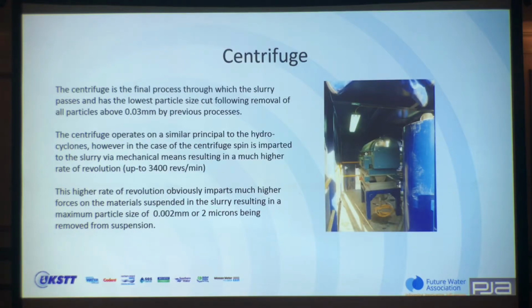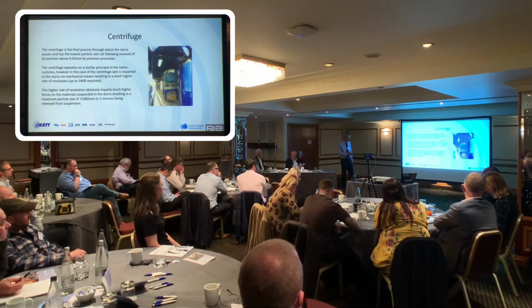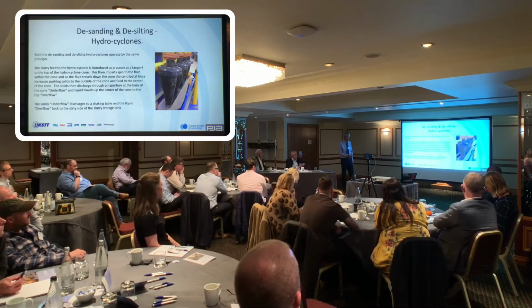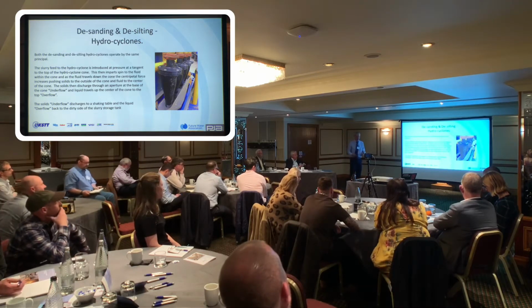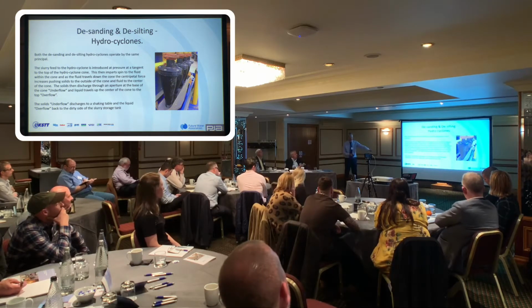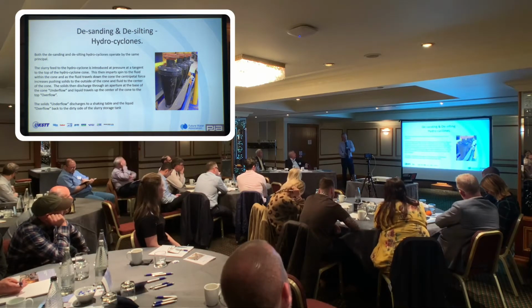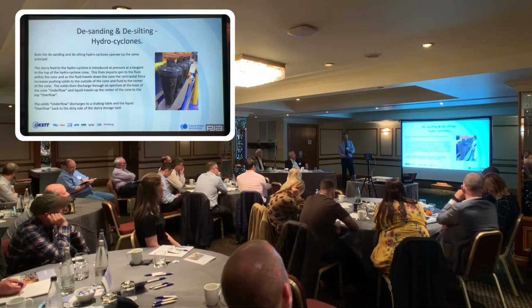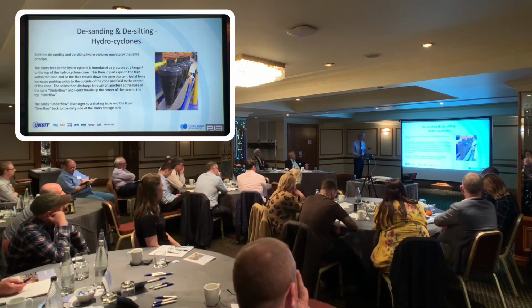The last process, or one of the last processes, is using a centrifuge. In fact, I missed a process. Yes. So all of these processes will discharge onto a fine screen. And what usually happens is that you get a filter bed on the screen. So if there's sand particles within the slurry, the filter bed builds up, and that further filters what goes on top. So all of your silt particles and your smaller particles will go onto that.